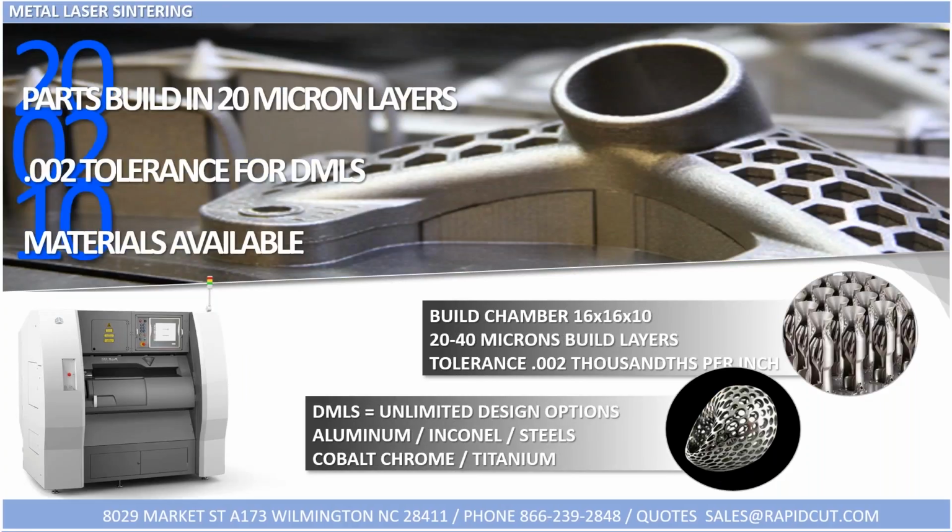Our final process that we'll look at today is the metal laser sintering. By far, in my opinion, the most exciting of the processes. The major reason for this is it's going to allow us to build parts in metals that we otherwise simply couldn't in the past. One of the best examples of that is the fuel nozzle that you'll see in the center of the screen. This was at one point over 16 different parts, fixtures, welding and setup, people were involved in order to get these parts created. Now they're simply grown in a single piece. So excellent example of how to best utilize this type of technology.